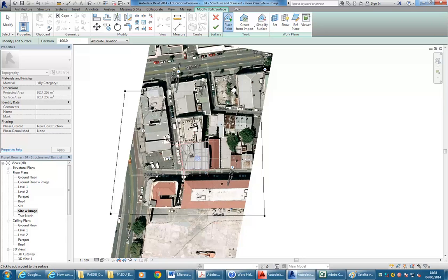That's just to give me a large area of ground to work with, and you can see then, as I was creating those points, how it makes your surface. It's just like connecting the dots, really. So it's not drawing in any particular order. It'll decide how the surface is connected. So you just set a height, and it'll then join everything to create a continuous surface.